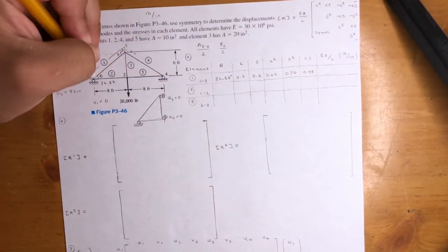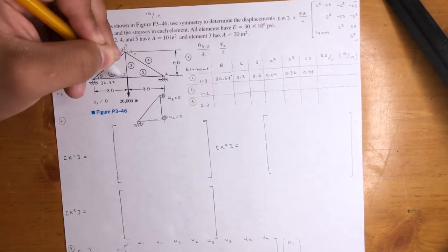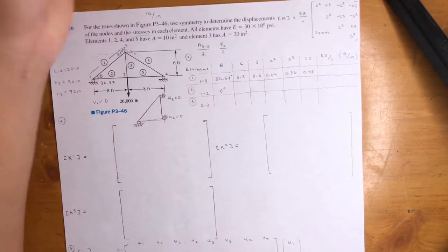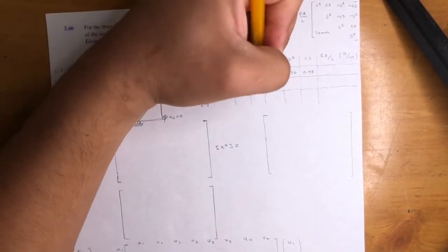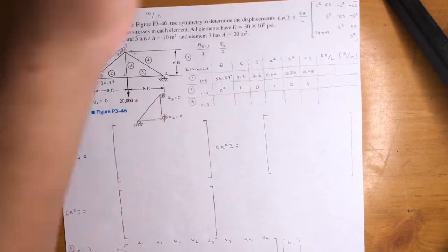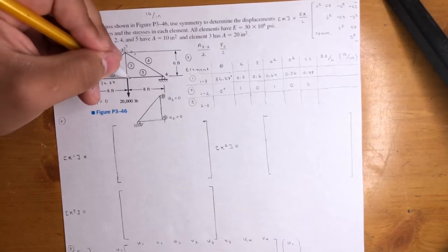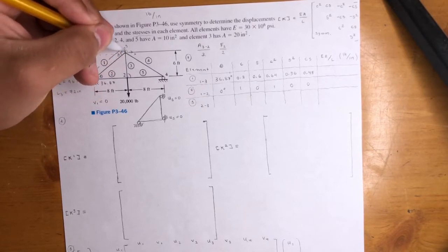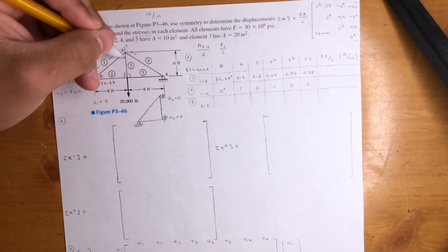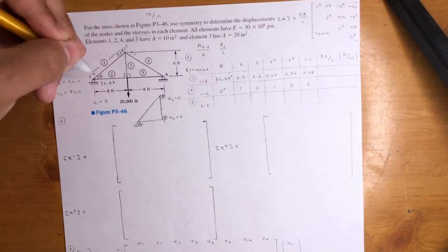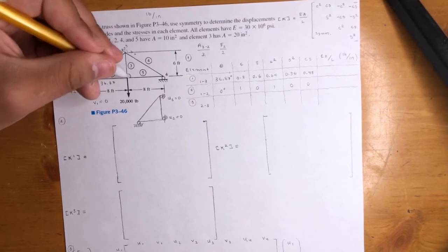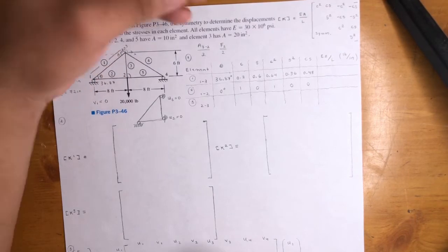Now the next one, from 1 to 2, that angle is 0, right? It lands right on the x-axis in our case. Because we're starting the axis right here at the smallest node. And relative to that axis, that's 0 degrees. And if you get the cosine and sines, you will get 1, 0, 1, 0, 0. Okay, that's just trigonometry. Finally, from 2 to 3, we went up 90 degrees. Okay, if you would have gone from 3 to 2, you would have used 270 degrees. Okay, because you went all around. And for this one, I didn't mention it, but if you went from 2 to 1, you would have used 180.